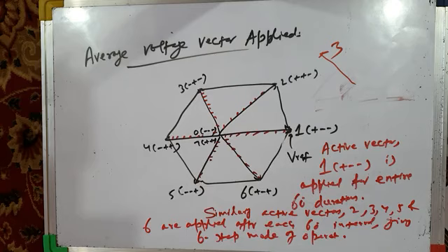And finally, if you make over-modulation with modulation index greater than 3, your 3-phase PWM voltage source inverter degenerates into a 3-phase square wave or 3-phase 6-step voltage source inverter, which we studied just a few moments back.